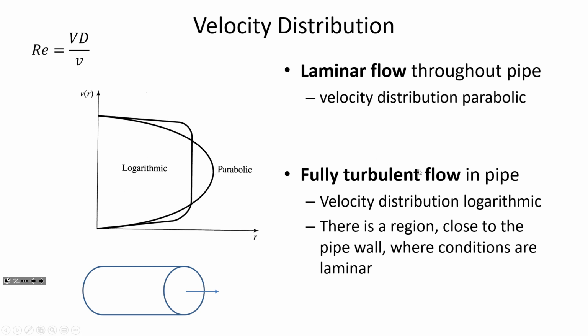And then in turbulent flow conditions, there's a logarithmic shape where at the edges of the pipe the velocity is very low, tapering to zero. But then there's a relatively flat average velocity across that profile. And at any given instant, in the case of turbulent flow, maybe at one spot the velocity is low and at another it is high. So over the temporal average, over some time period, it would average out to a flat nose in the logarithmic fully turbulent flow profile.